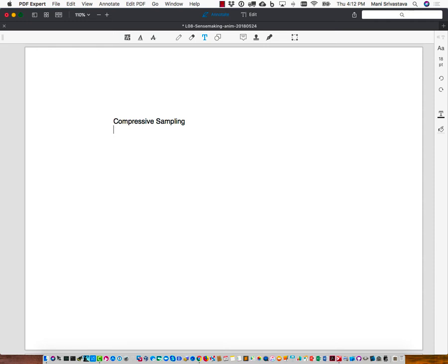was that the underlying physical signal that you are measuring is being generated by some sort of a physical process which is sparse in some aspect. So for example, it may be a physical process which has a small number of parameters. So if I think of all possibilities of that process, then what we are really trying to do is trying to measure what the values of those parameters are. So the example I had was, imagine it was a sine wave, and so there are only 3 parameters. So if I think in terms of the parameter space, then it was very sparse out there.